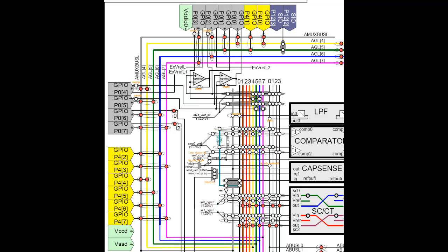Notice the red and white circles. They depict switches between signals. The red switches symbolize low resistive switches with an on resistance of about 200 ohms. The white switches are smaller and have an on resistance of about 870 ohms. The amount and mixture of switches provide a good compromise between a full cross-point switch and keeping the cost and area and route capacitance to a minimum.